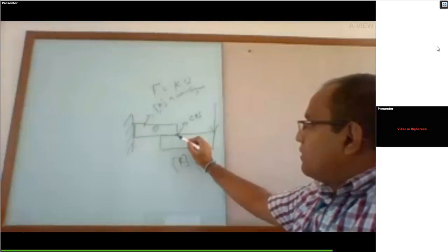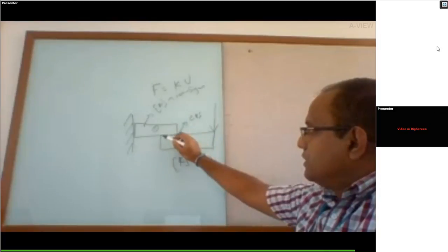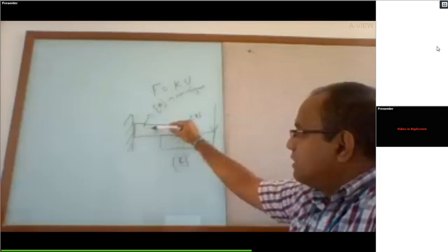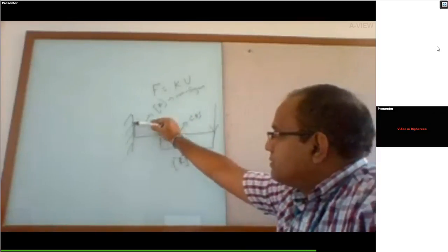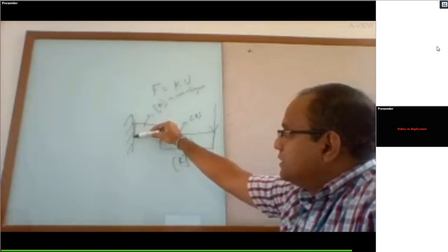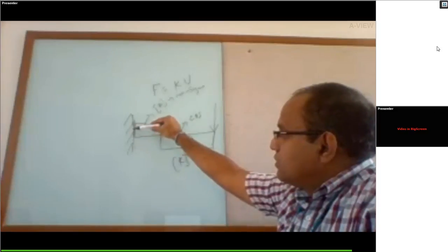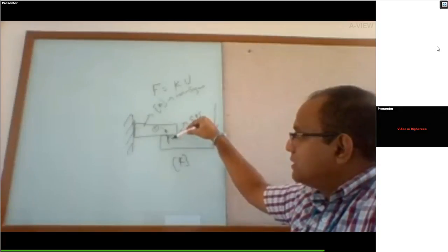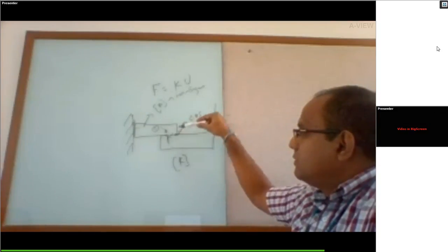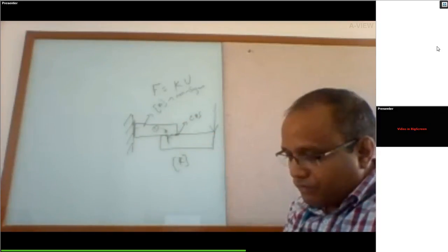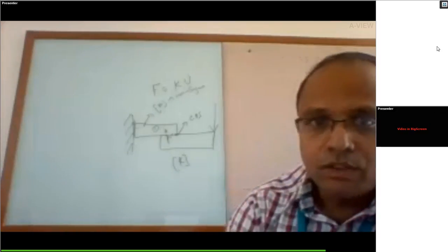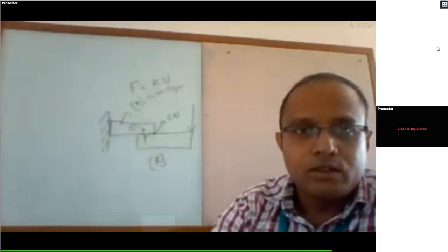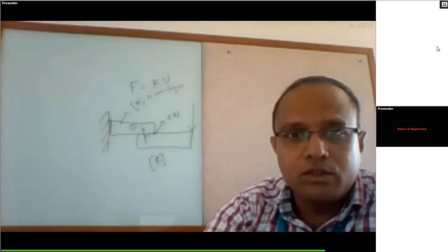The singularity can be avoided if you can establish some relation for this component from this component. This deflection we are constraining here, so the constraint can be established as a relation. The relation can be established through couplings here. Couplings are constraint equations, so constraints are applied only to master nodes.